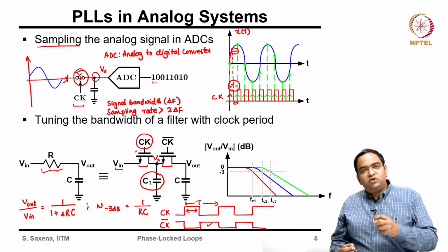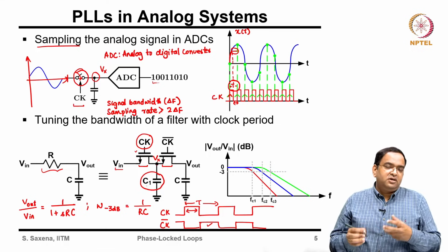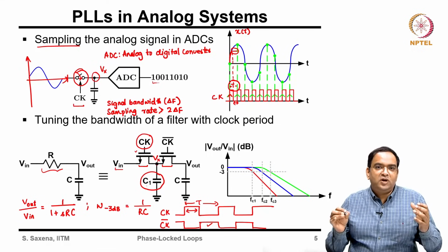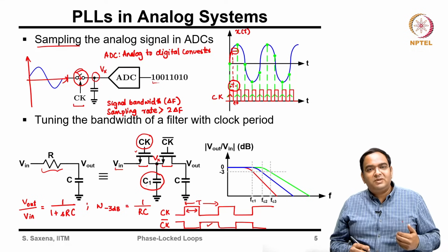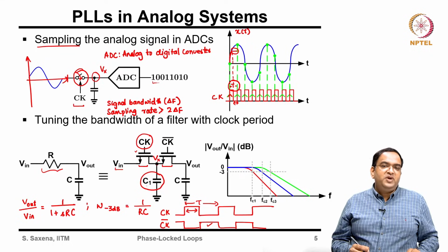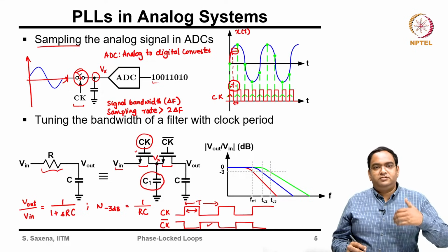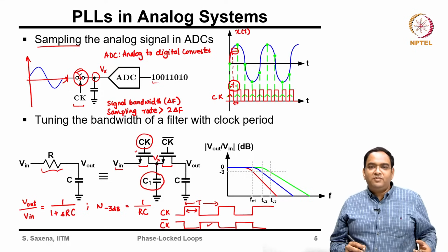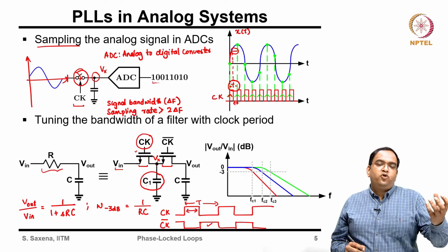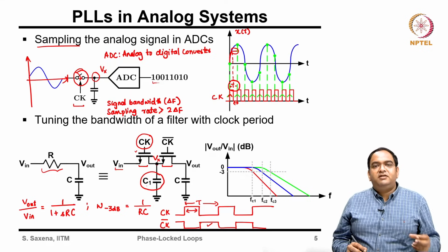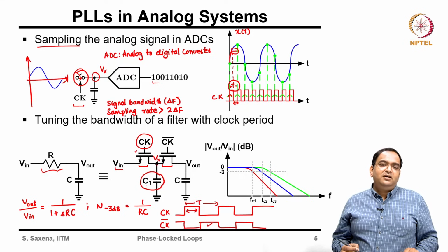So, it is taking more and more charge from Vin and transferring to Vout. Effectively, the average charge which is drawn from the supply and transferred to the capacitor C is going to be more. So, in literal terms, if using some component I am drawing more charge per unit time, effectively it is behaving like a low resistor.